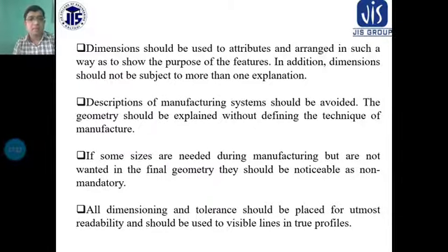And in another case, all dimensioning and tolerances should be placed for utmost readability and should be applied to visible lines in true profiles. Basically, all dimensions and all required tolerances should be placed for the utmost readability. If the dimensions and tolerances are not readable, then you cannot put up your dimensions properly.